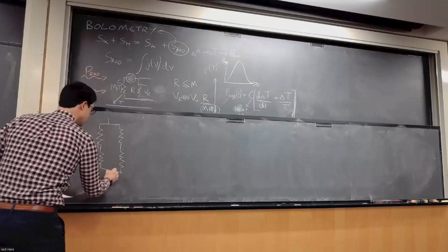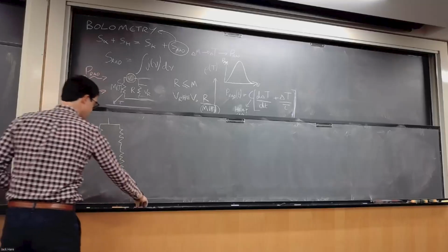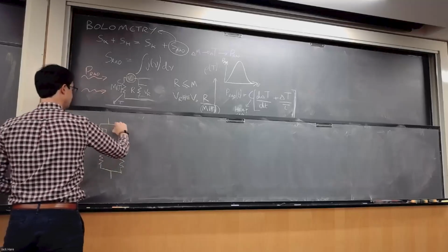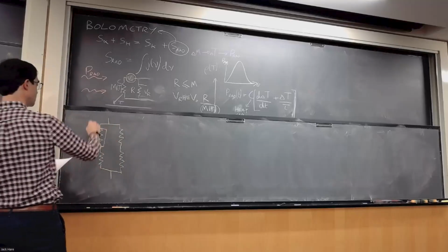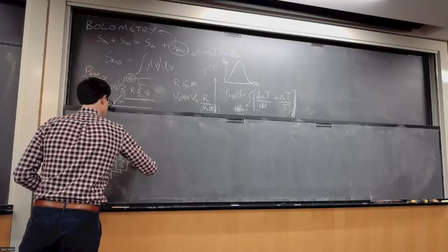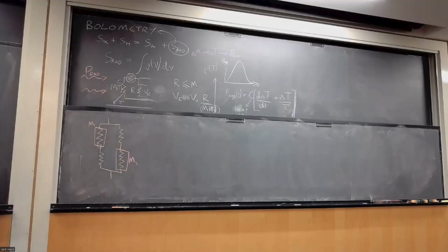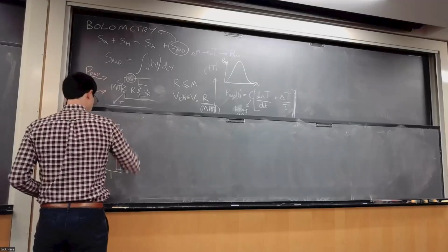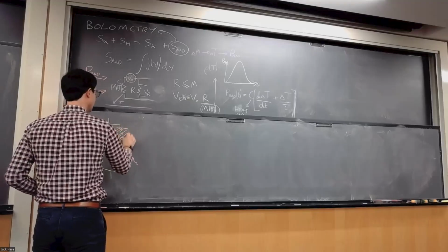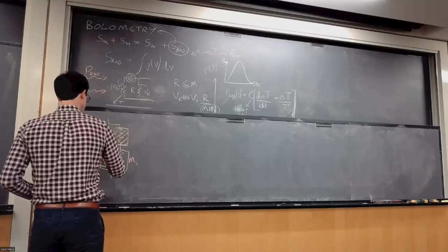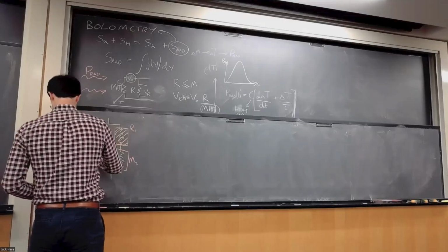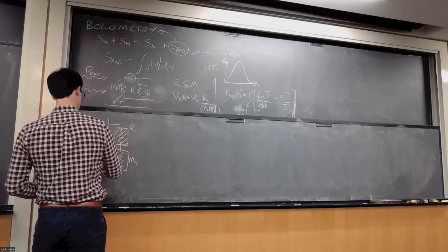And we connect these resistors up, and the clever thing in a bolometer is we allow 2 of the resistors to see the plasma, and these are the ones we call the measurement resistors, M1 and M2. So you can imagine these resistors just having a little window that allows them to see the plasma, and the other 2 resistors cannot see the plasma. They have a large lump of metal which gets in the way, and these are the reference resistors, R1 and R2.